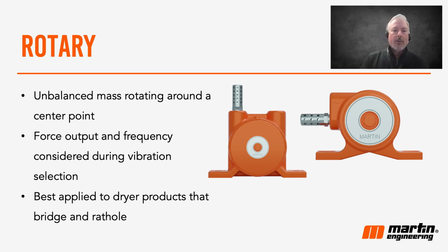So now we'll look at the rotary vibrators that are out there. You see photos here of electric, and the other three are all powered by compressed air. They operate at a wide range of forces and frequencies, and typically we'll recommend lower frequency, higher amplitude models when dealing with higher moisture content. So that's one differentiation that we use on the frequency of the vibrator.